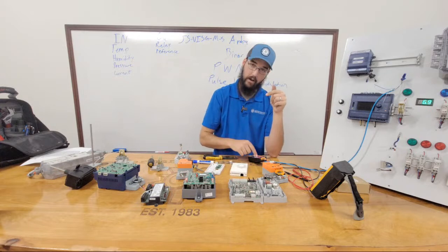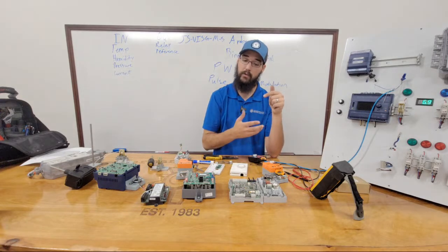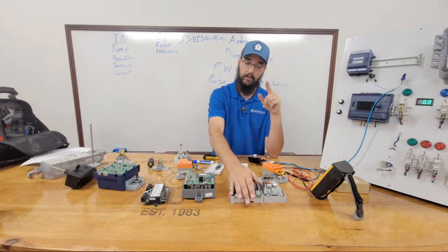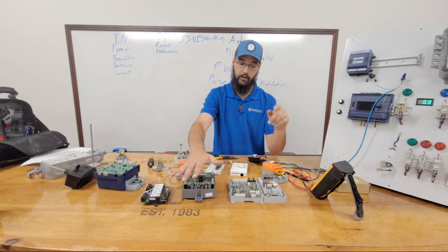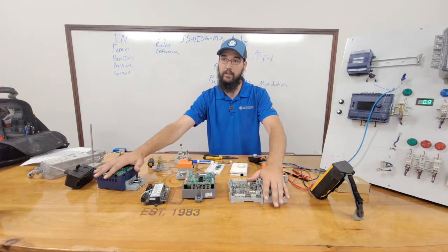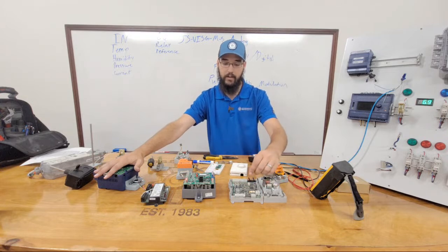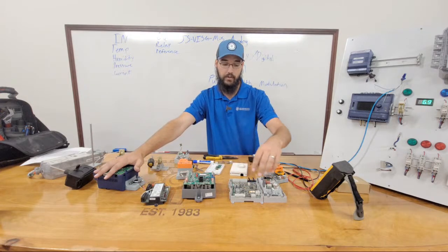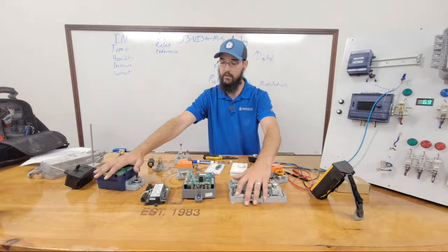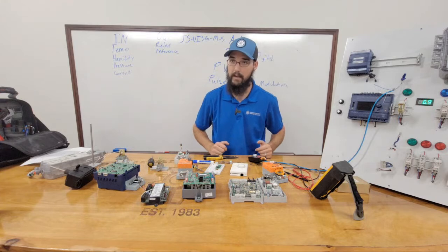But if you do not have a signal generator when you're testing this and you're trying to only use the controller itself, be careful not to just condemn that controller, because you're talking $1,000 or more to get one of these replaced and reprogrammed and configured, because these aren't as simple as just a plug and play. They have addresses, they have specific program features and functions, and there's a lot that goes into this that requires somebody with a laptop and some know-how. So this is not a small decision to say that any one of these is bad.